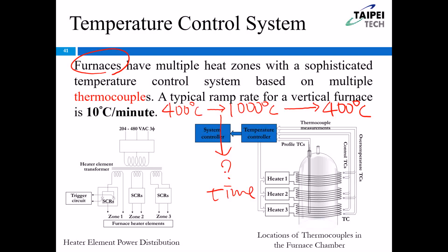When the quartz tube is cooled down to 400 degrees Celsius, then you can unload the silicon wafer. So here and here, it must take more than 1 or 2 hours. I give you this temperature and the temperature ramp rate just to show you it's a very long process. It's a waste of time. It's really a waste of time.